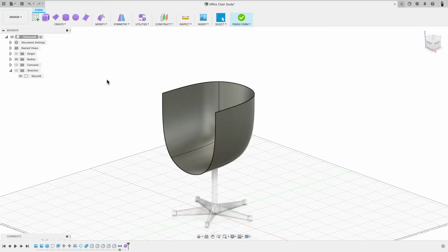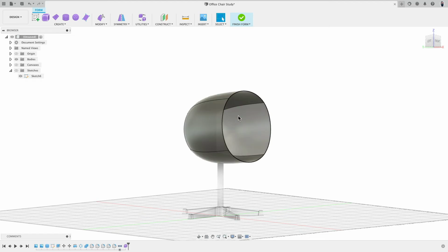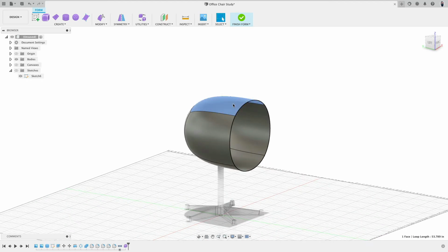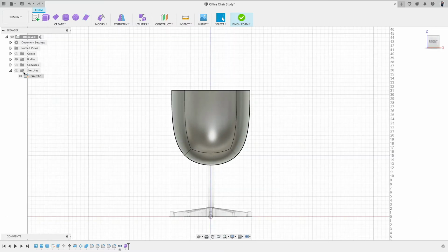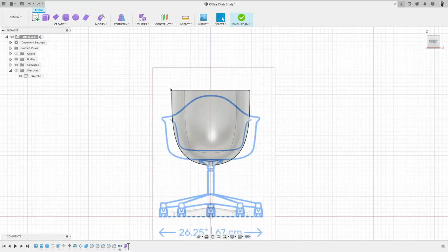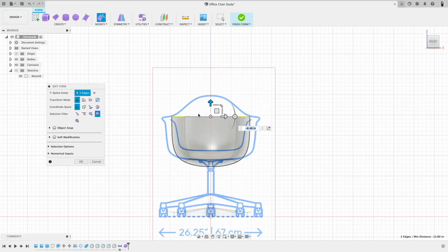So this time we will delete these two faces. And whoa, you see how this thing opens? If I delete this or delete this, there you see what's happening. So what we can do now is actually the following. Okay, so here's my modify. I will work on just edges I selected, bring this one down, this one I bring up.